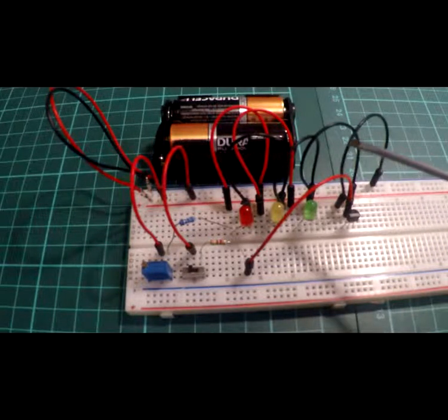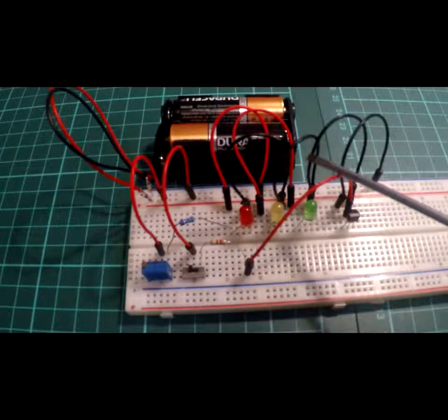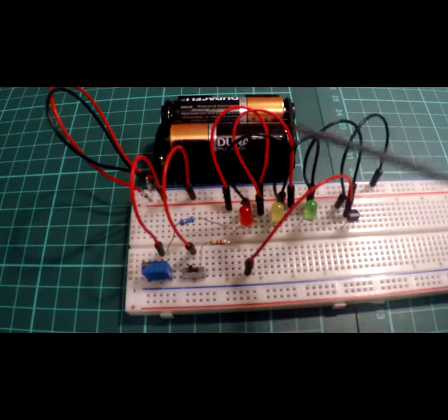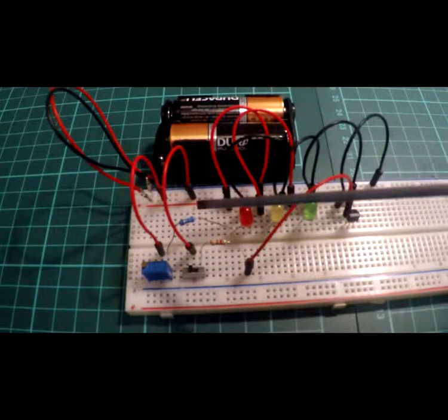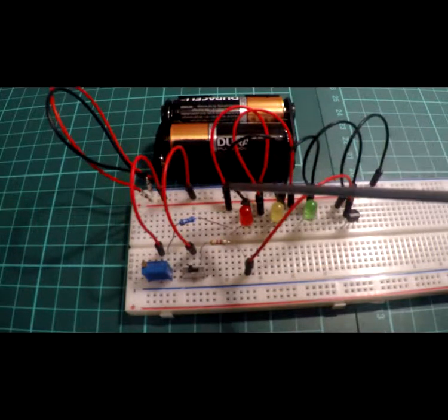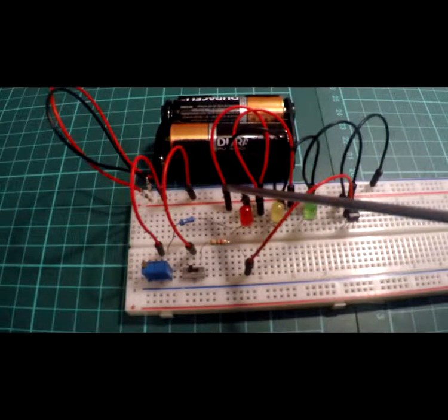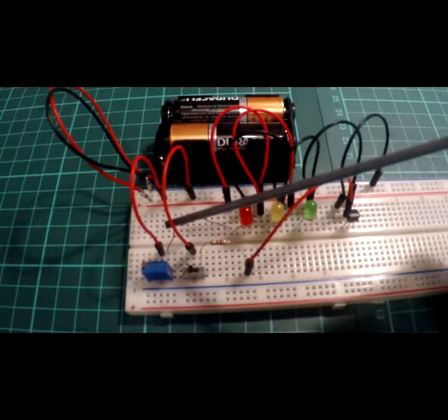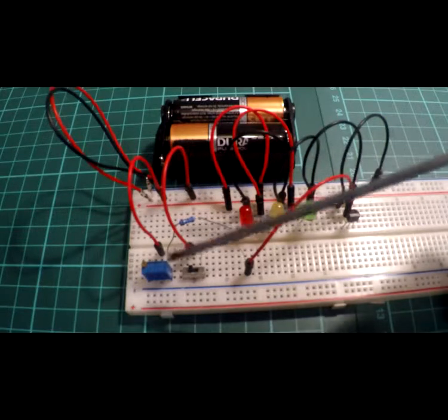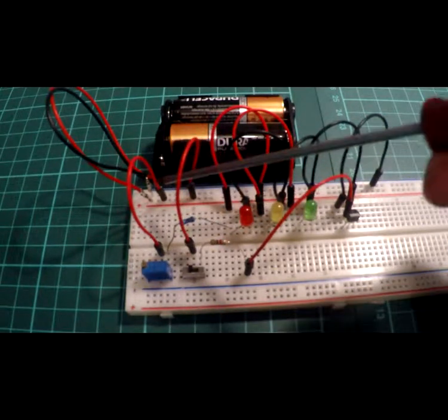The emitter is connected to ground, and the collector then goes to the ground of the LEDs, and the LEDs are just daisy chained together. As you can see, they're literally just all in parallel, daisy chained up. Now at the end of all this, the power comes back this way through that ballast resistor and then through the trimmer and back to live here.